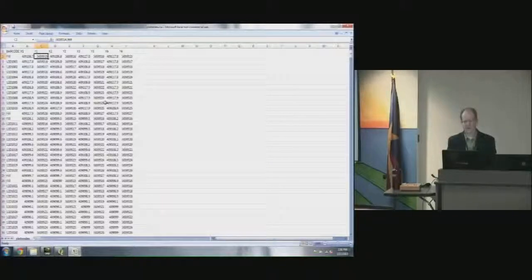And to be truthful, we kind of generated this just based on our knowledge of our plot using some software that we have available. But you would need to generate this file on your own for your specific field. And there are multiple ways to do that. You can go out with your GPS rover and actually measure those 4 corner coordinates of your plots. Or you can actually just do calculations.